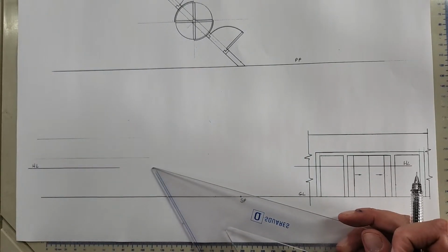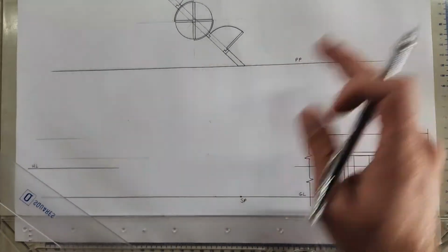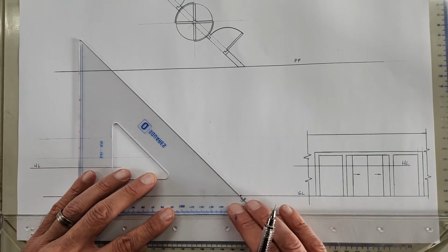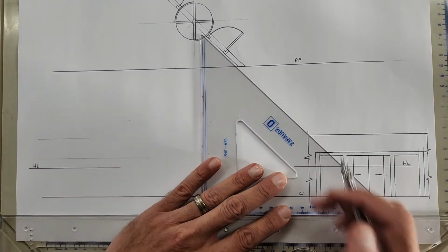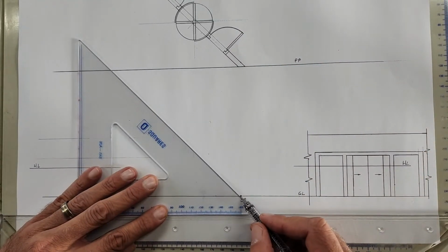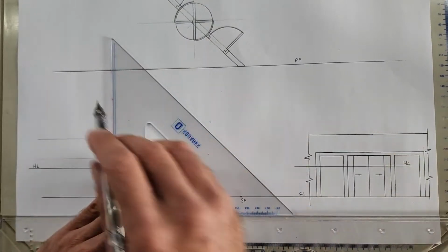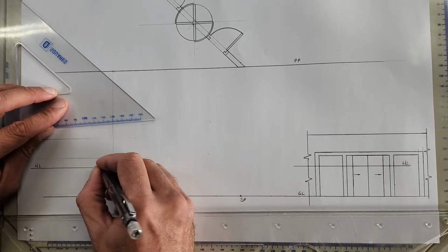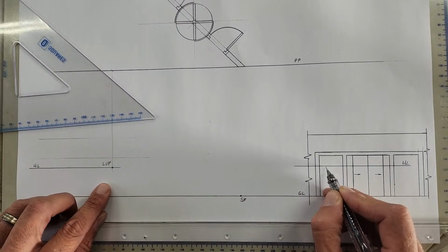I'm hoping that all of you have done some tests with this before you actually do the drawing because it isn't as simple as it might seem. So please do a test before the time. So at 45 degrees from the standing point, I've placed the standing point on the ground line to the picture plane, bring that down to the HL. And the HL here, left vanishing point, is at 1.5 meters.